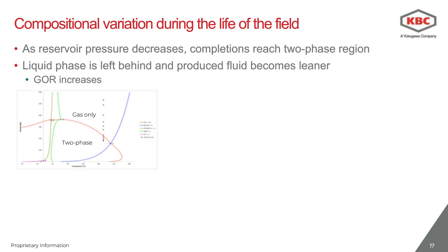At this point, the well starts producing a two-phase system, the two-phase system of gas and liquid rather than gas only. And because the liquid travels with a different speed than gas, the liquid is left behind, and the produced fluid is presumably becoming leaner as the production goes on. The GOR, therefore, would increase probably, I would expect, during the life of the field.